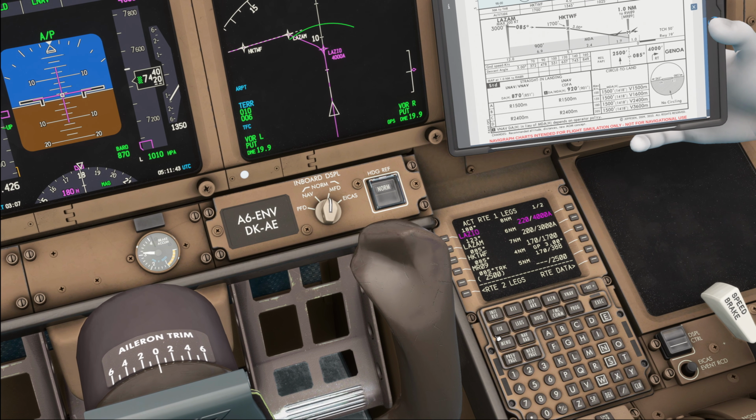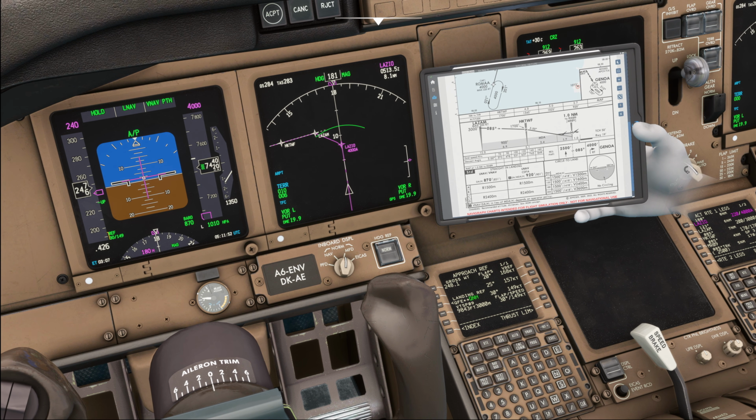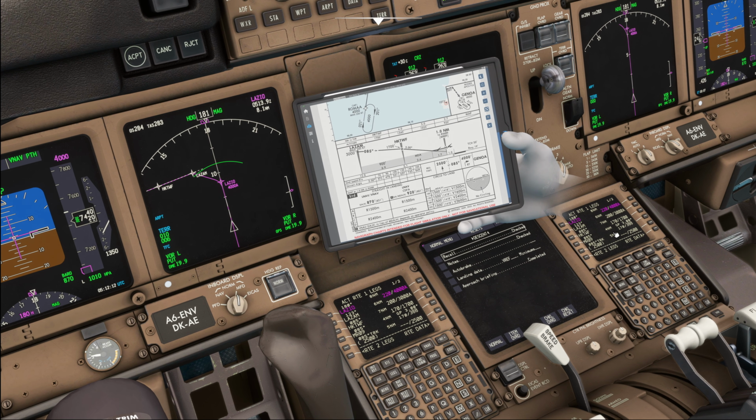Now that basically concludes the mandatory setup of our FMC. Of course, we are also going to insert a flap limit, we are also going to set an auto brake and stuff like that. But this is the important stuff, verifying that your legs page indeed matches the procedure accurately and ensuring that the minimum is selected. Now with all of that out of the way, let's go ahead and read the descent checklist in order to ensure that we haven't forgotten anything.